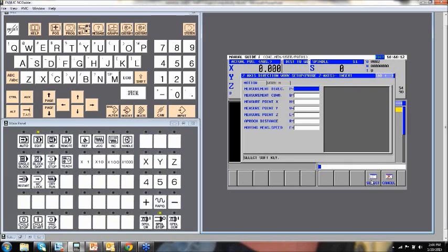If we select the Z-axis, again, it says fill in the blanks. If the control is going to give you any selections, they're down here as a soft key, so we'd say Z minus, measurement condition, 0, 0, 0, approach speed, and just fill in the blank.